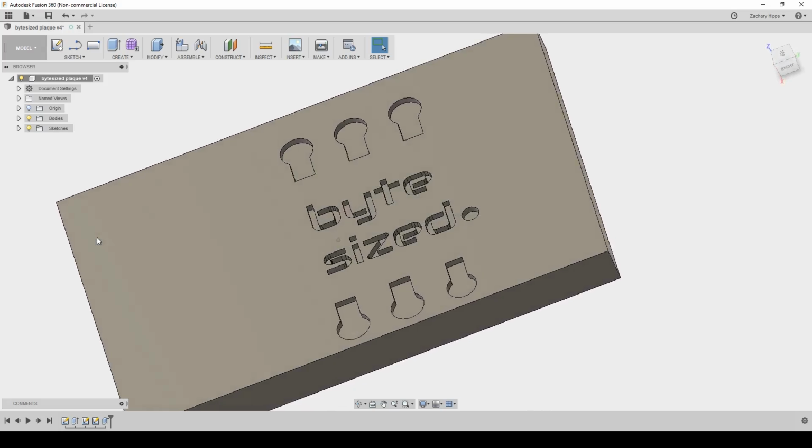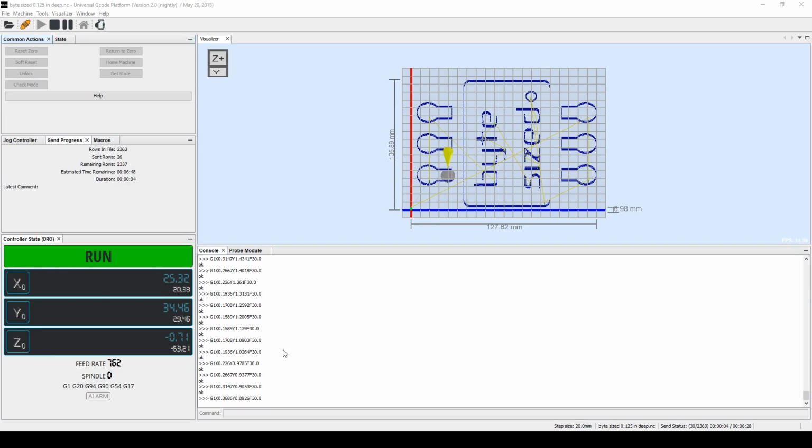In this video, I'm going to finish a project that has sat in my office unfinished since 2011, my desktop CNC machine. A CNC machine is a tool that can automatically cut a design out of a material like wood or metal. The design starts out on a computer and is converted into machine instructions called G-code. The CNC machine will read the G-code one line at a time and remove material until the entire design is cut out of the material.